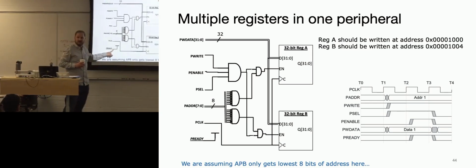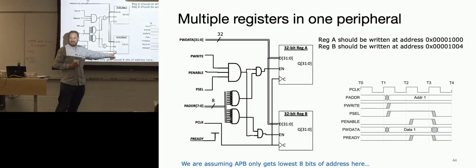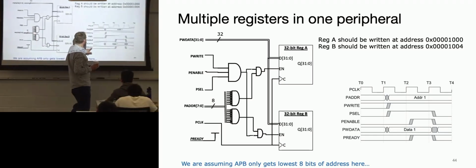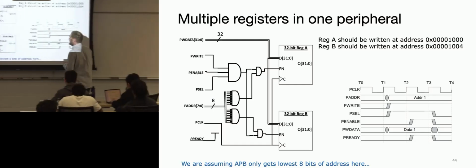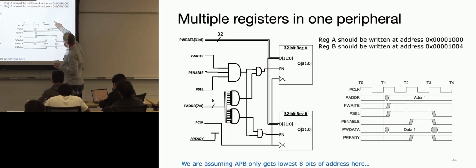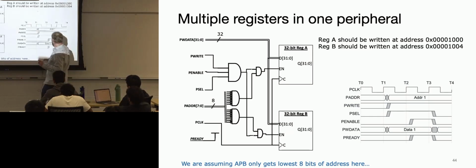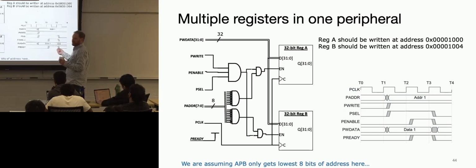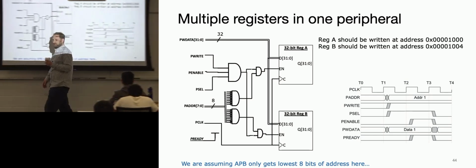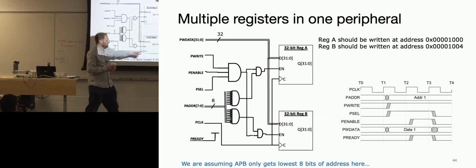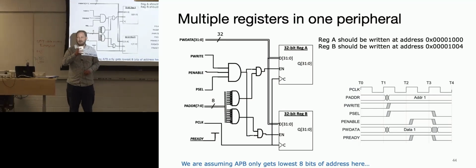It doesn't need to, because the registers will complete this task immediately on the falling edge. Let's see, P enable's high on this clock edge, right? This clock edge will latch in all the information from data, wherever data is here, right? So all those conditions are true at this point. And because it happens instantaneously or close to, we don't have to hold this line low for a period of time. So we're just going to say it is high. We'll talk about wait states where we actually do have to pull this thing low later.